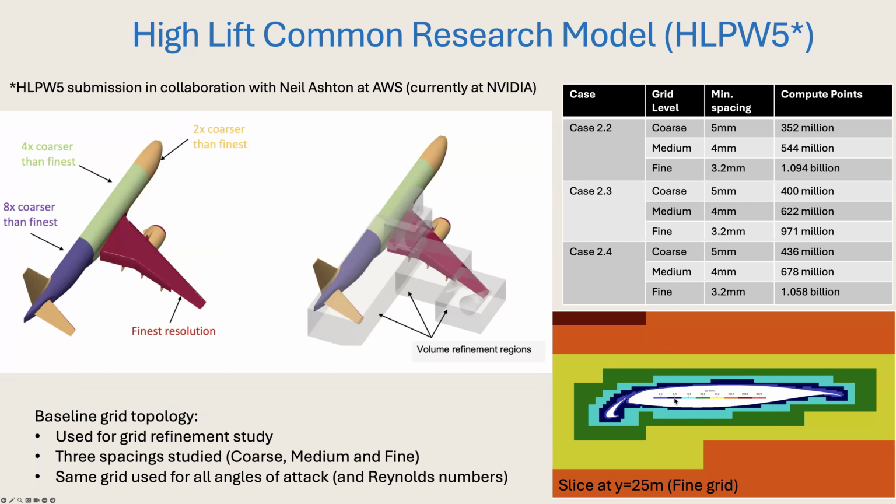And then in his coarse grid simulations, he noticed chine vortex, the wake coming from slats that creates pizza slices, and maybe flap separation, and even maybe the effect of the wing on the horizontal stabilizer could be an issue. So he created volume refinement regions.